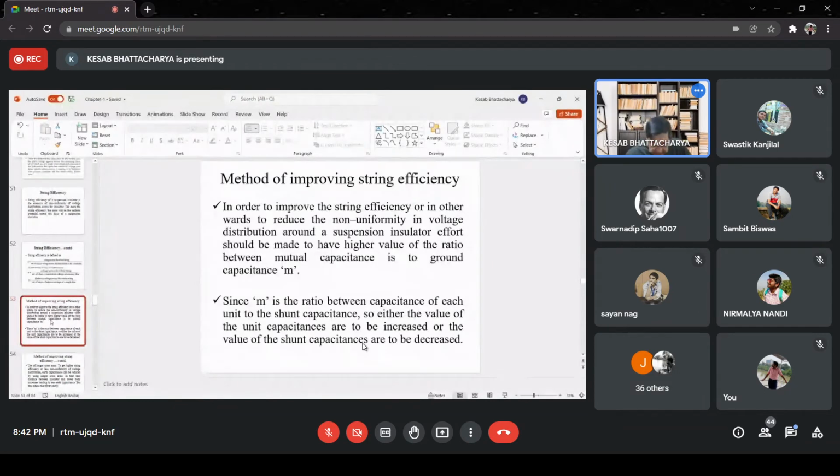Since the disks used are identical, their capacitive reactances are the same. Therefore, if you cannot improve the magnitude of the current flowing through them, you cannot improve the voltage distribution.